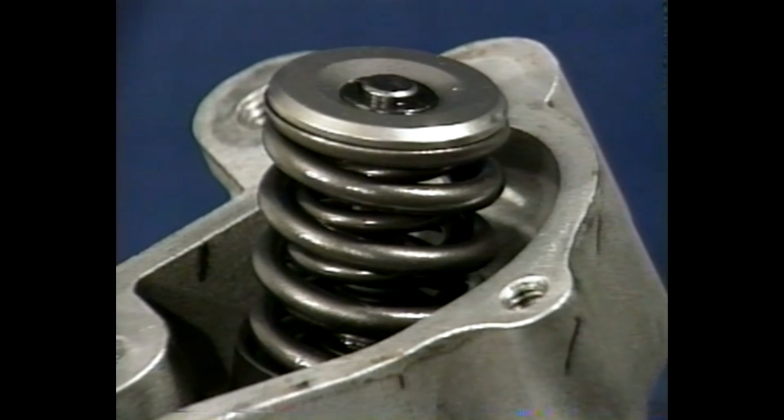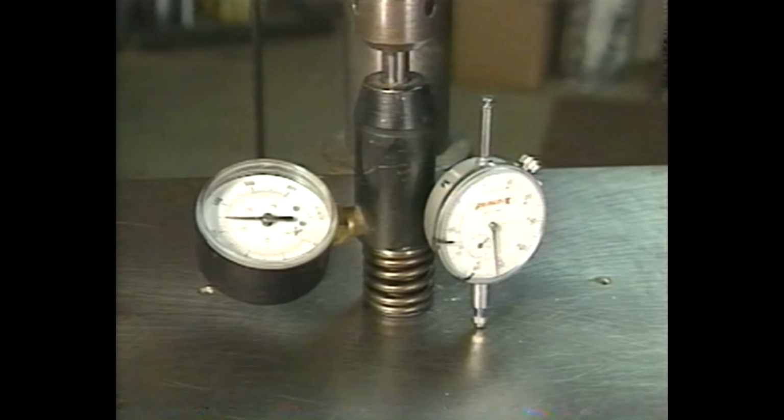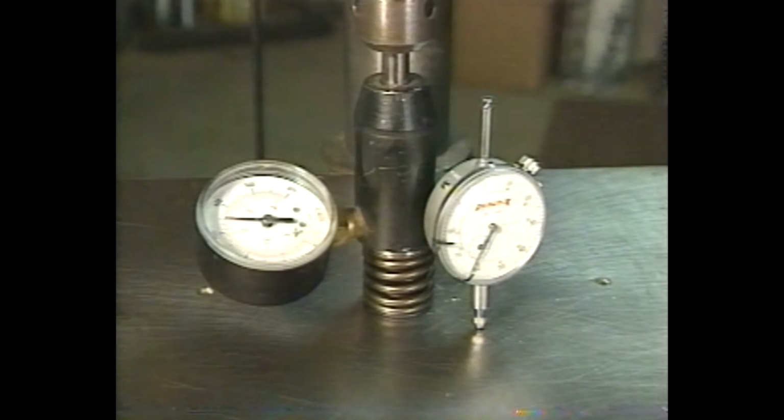There are normally only two reasons why we find a bent push rod. It is either too weak to handle the valve spring pressure, or the valve springs have become coil bound. Most cam manufacturers will recommend the type of push rods they want used with their high lift cams and heavy valve spring pressures.